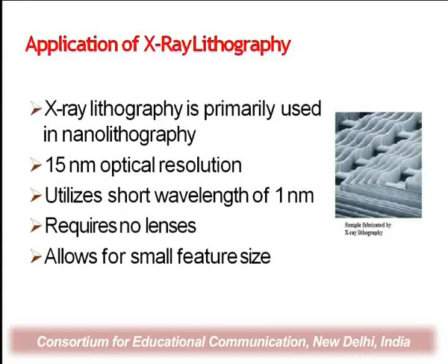What are the disadvantages of X-ray lithography? In X-ray lithography, we use primarily nanolithography, and we can get 15 nanometer optical resolution. X-ray lithography utilizes a short wavelength of 1 nanometer. It requires no lenses, and it allows development of small feature size devices.